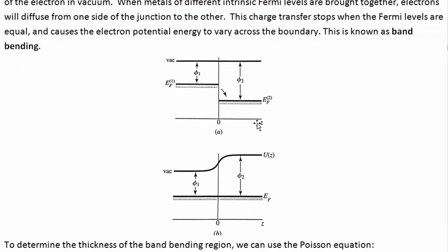So when two metals are connected, electrons are going to move such that it creates an electric potential difference across the junction. We remember from previously that the metal with the lower work function is going to have electrons transfer from it over to the metal with a higher work function, because they basically drop to a lower potential energy when they jump over there. So electrons are going to transfer until the Fermi levels are matched in the two metals.